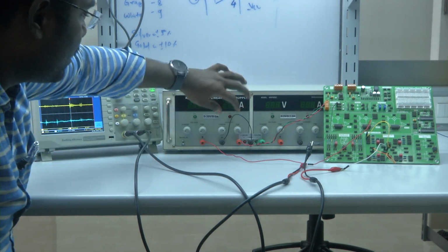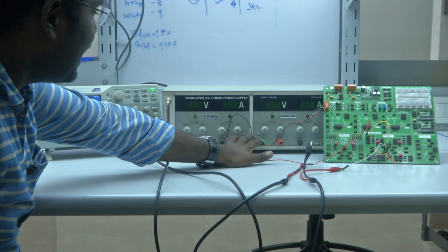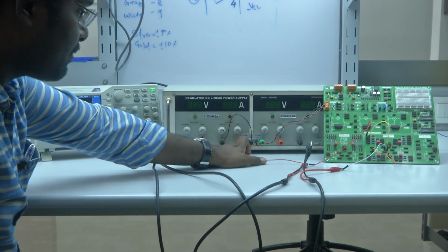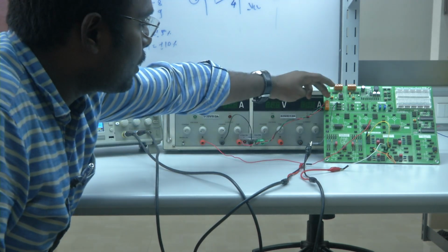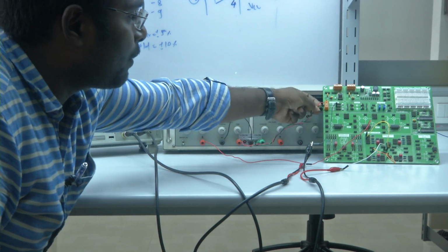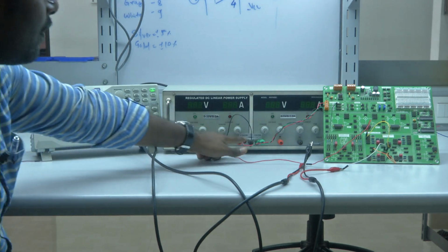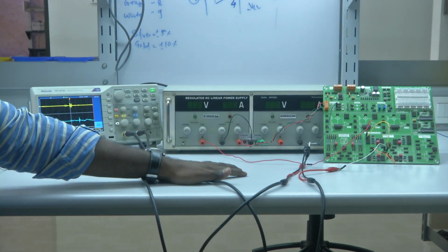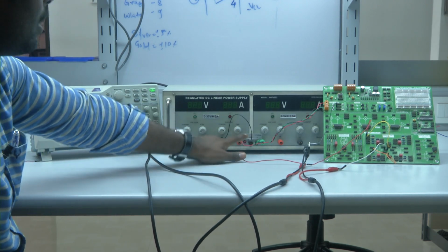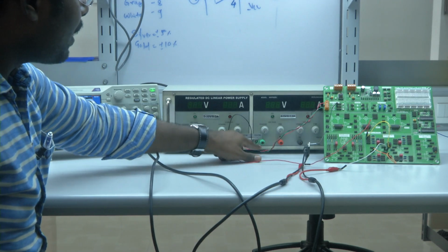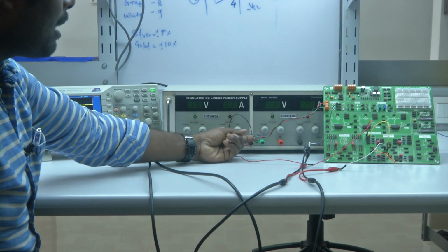The DC linear power supply that we have has dedicated power sources for plus 15, minus 15 and ground. We have connected the plus 15 to one side of the main power, which is the positive terminal. Even though the board shows plus 10, minus 10, we have connected 15 because the operational amplifiers can withstand up to plus or minus 18 volts. Since we have a dedicated power supply, we have directly connected it, and for the negative, the green wire has been connected to the other side.